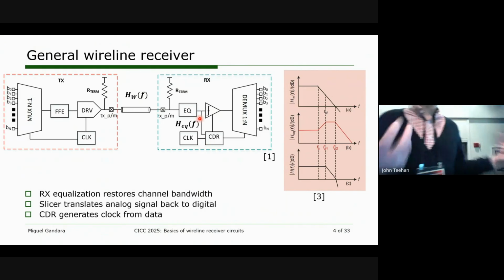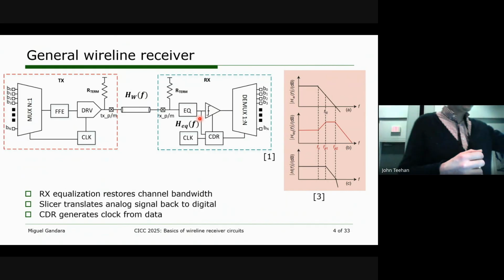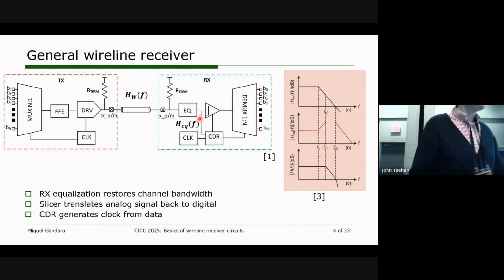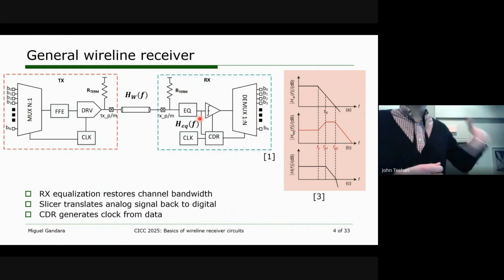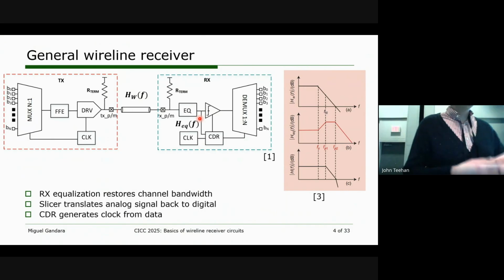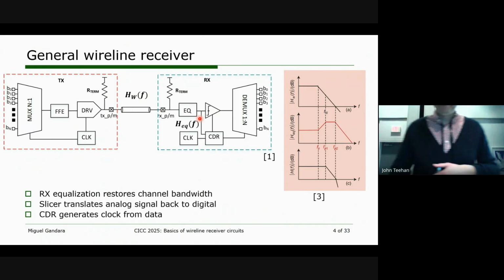What this feedback loop does is it provides us the clock data from the signal. So this feedback loop actually helps save us a pin because now we don't need to send the clock. The clock is included within the data.